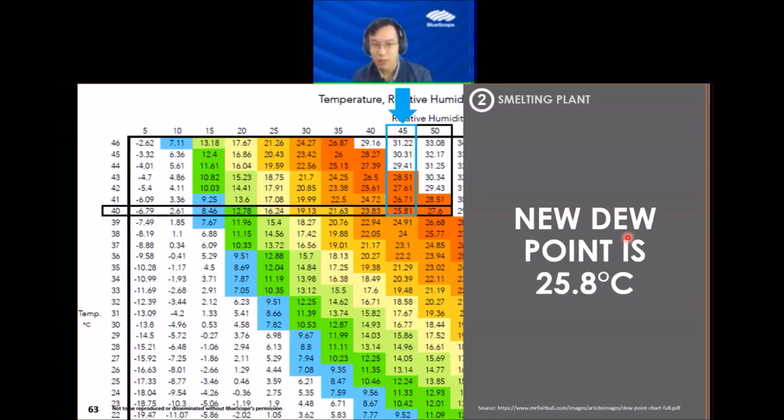So let's say you eliminate that risk externally, you're looking at the surroundings and even your stacks. What kind of material are you burning to produce the energy? Let's say the chimneys themselves release corrosive substances like sulfur dioxide, chlorine, any types of industrial emissions that could also jeopardize the roof, then you are supposed to look for a product that is longer lasting.